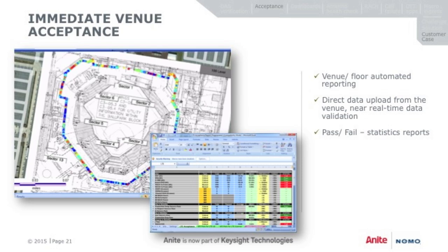And also from a coverage standpoint, if you notice the map that I'm showing you, right above sector 1, there is a small area where you don't see any coverage, you don't see any bins or data points there. So you can always do a quick check of your walk route to see if your field tester covered your entire venue or not. In case you've missed any locations, instead of coming back 1 week later, you can do a quick check to see if all your area was covered. And if not, you can collect it right away and rerun a report to see if it was covered.